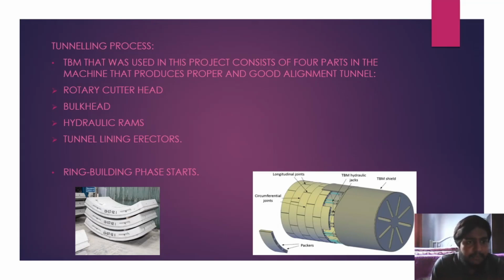The main principle of this method is excavating the ground along the route of the tunnel, constructing the tunnel, and burying the tunnel by backfilling the route with earth and compaction of materials such as sand and quarry dust. Strong supporting beams are placed in order to support the trench from collapsing. The construction method is relatively inexpensive and usually used for subway construction.